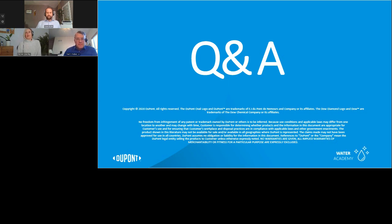And I wanted to just address the question on resins, why use this resin versus that resin. And when you're changing to a condensate polishing application, is that going to be a different selection of resins or the same? That would be a different set. We have a set of resins that are recommended for working mixed beds. We have a different set of resins for polishing mixed beds, and we have a third set of resins for condensate polishing. So the 3 different major areas where you would use a mixed bed each would have a different list of resins.